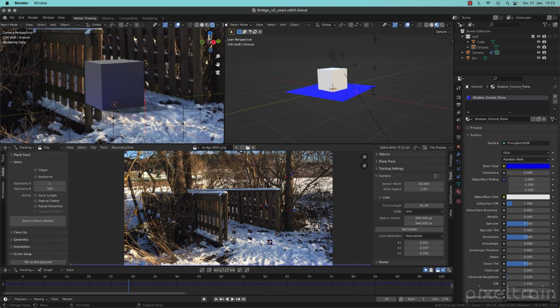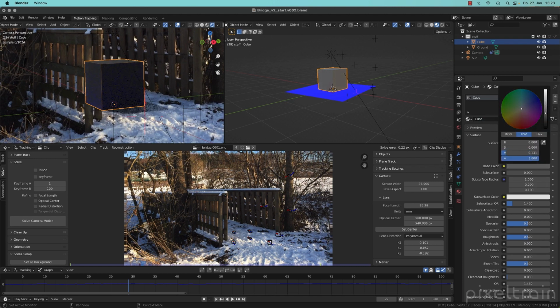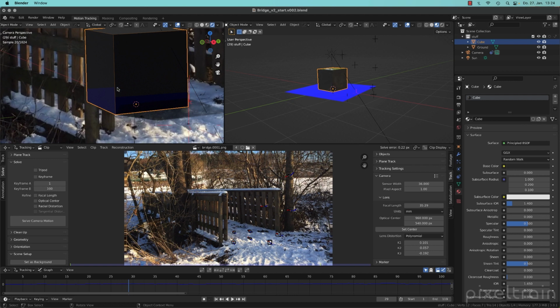And by the way, reflection, let's go to the cube and make a material. I say I have a not too bright base color. I don't want to have this rough, so I go down, down, down, down. And I think you see it here. Maybe we can make this a little bit more obvious. You see that we also see the indirect reflection of this floor. So the Shadowcatcher also delivers reflections for us. So that's the important part.